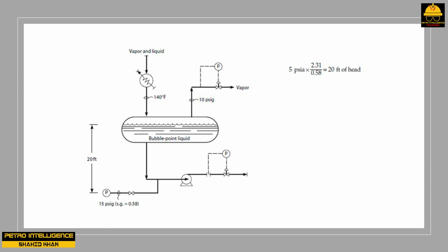The answer is no. Unfortunately, it is not only the pressure of the liquid at the pump that changes. The composition of the liquid will also be altered. As the pressure in the drum increases, additional lighter components dissolve in the liquid. The composition of the liquid then becomes lighter. The vapor pressure of the liquid will also increase by 5 psi.